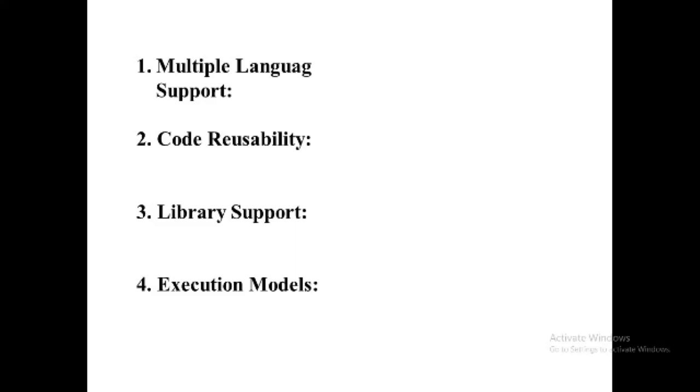It supports the programming methods of IL, LD, and SFC languages. You can switch back and forth between IL and LD while you work. You can program your own function blocks, and a wide range of utilities is available for configuring the special function modules for the MELSEC System Q. There is no need to program special function modules. You just configure them.